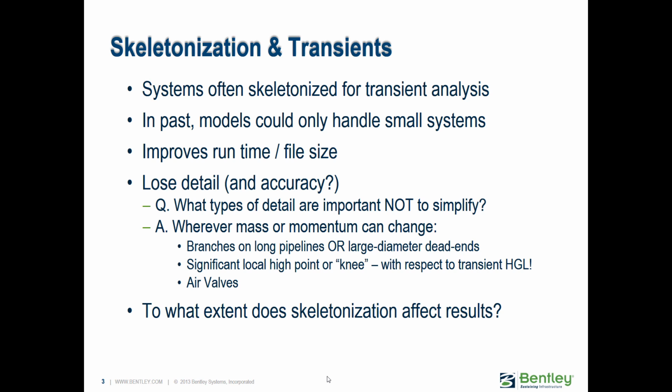And it may reflect and possibly interact with other waves or areas closer to the area that you're analyzing. Those things really should be included. Versus, imagine a full city model. If you're modeling a pump shutdown way in the south corner, all the way in the north side where everything is branched out or looped, most likely by the time the transient gets there, it has branched off and gone through so many different paths and changes in direction that the transient energy has dissipated and dampened out.